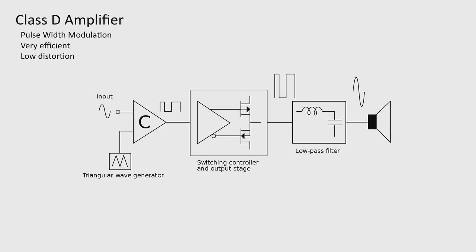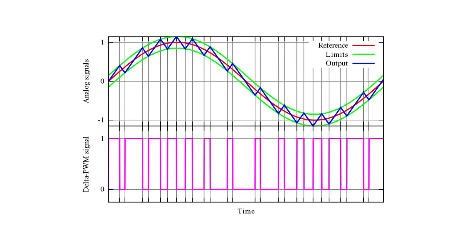We've talked about pulse width modulation before. That's what's happening here. You're taking your amplifier and you're turning it all the way on or all the way off at a much higher frequency than, say, if we're talking about audio, a much higher frequency than the audio. Or if we're talking about an RF signal, we're switching it constantly from off to on, 1 or 0.